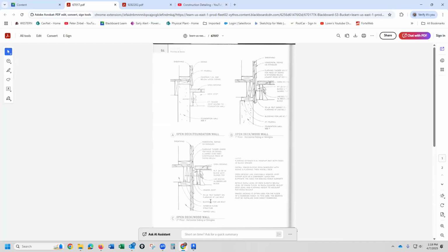If you find a better one, or one you like better on the internet, you're welcome to go ahead and use that. So when a lot of people talk about detailing a building, this is the part they're talking about, where you really get into the nuts and bolts and the fine detail of how this thing actually goes together, and how do we keep it so that water doesn't get into the house and how it's structurally functional. So this is really kind of your first, quote unquote, detail. When people talk about doing a detail for that, they're probably typically talking about something like that. We've got to figure out how this deck connects to the house.